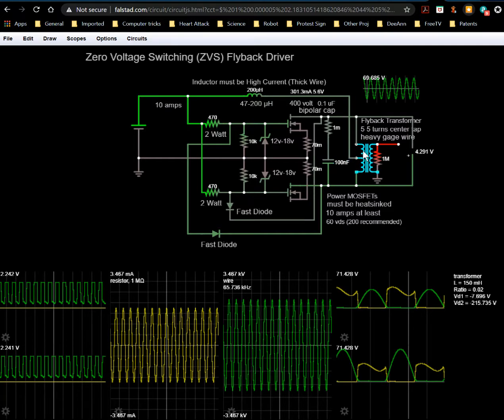Now, of course, in another video I was talking about how inductors don't really work that way, because they only store energy as long as there's current flowing in them. That's why you have a freewheeling diode on an inductor, because it tries to maintain the current flowing through it when you remove a power source, and the freewheeling diode allows it to do that. If you didn't have that freewheeling diode, there would be back EMF, or the flyback effect, which generates a very high voltage across this, whatever voltage it takes to try to maintain that current flow.